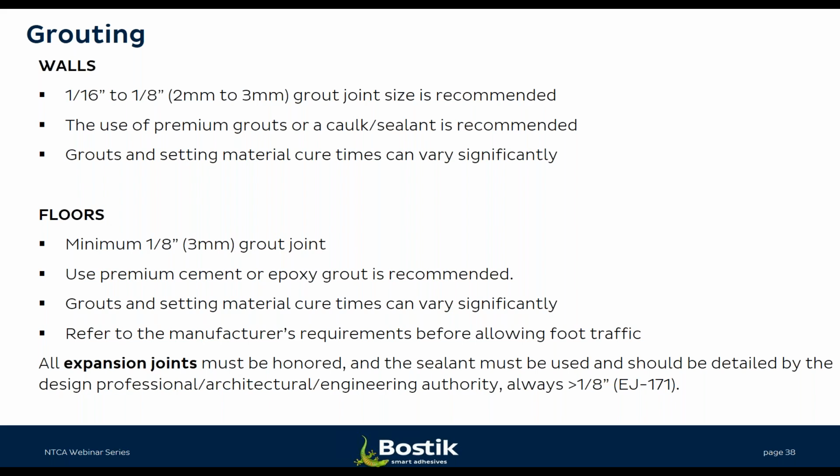From a floor application standpoint, the minimum joint size is 1/8 of an inch. What we generally see, again, would be epoxy or premium cement-based products in these applications. And in terms of these grout and setting materials, there can be a significant amount of cure time variance. So you really want to take into consideration cure times of both the grouts and setting materials, both before grouting and allowing people to be back on top of your floor during the construction process. So this is really of a critical nature. This is where those new age type mortars come into play in delivering a faster cure time.